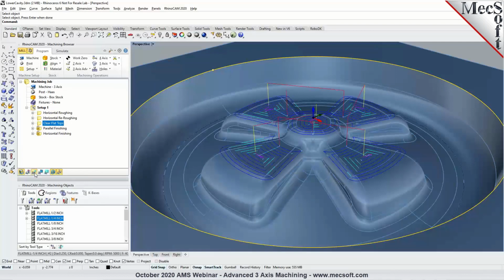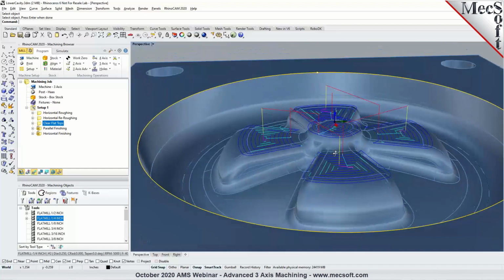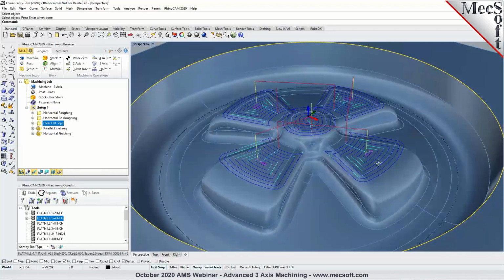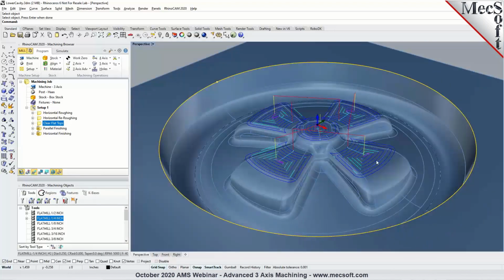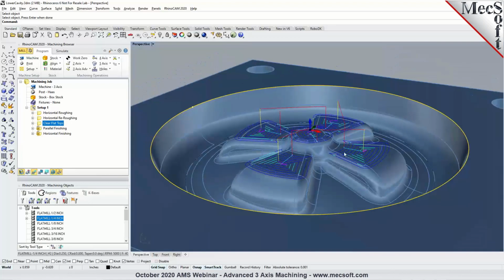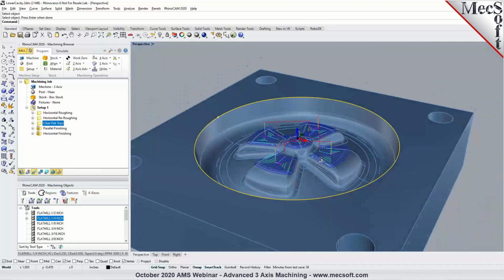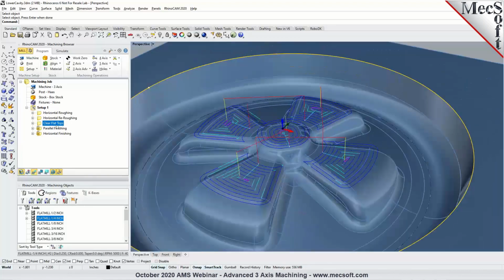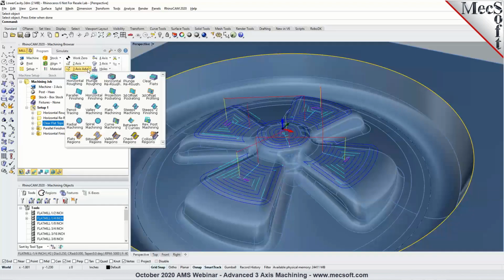Let me go ahead and display the toolpath in here, and you'll notice that the clear flats machining automatically identifies the flats from your 3D geometry and creates a flat area machining toolpath to clean it out. Again, the clear flat tops machining is available as part of our advanced 3-axis methods, which is included in Pro and Premium configurations of our mill module.